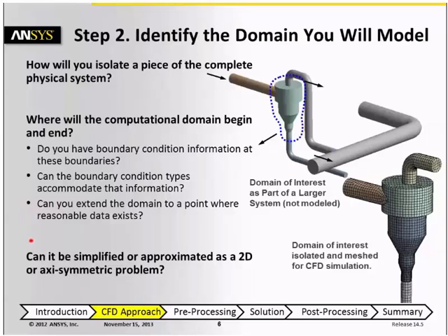Finally, always consider whether the problem can be simplified as a two-dimensional or axisymmetric problem. When this is the case, you can get just as valuable information, but it will only take a fraction of the time needed for a full 3D problem.